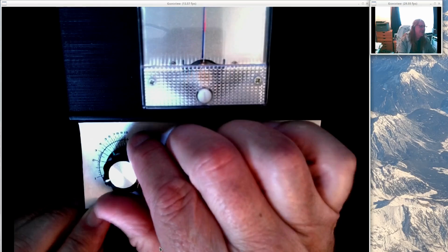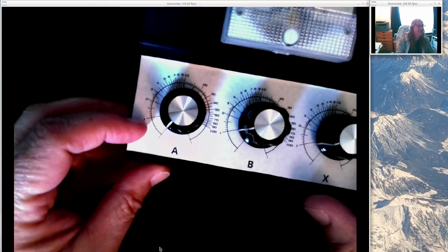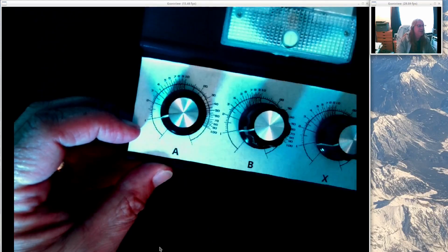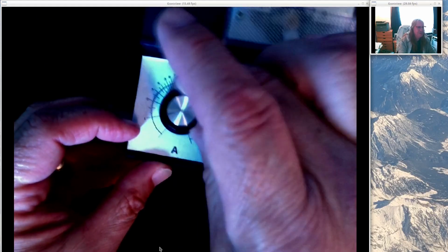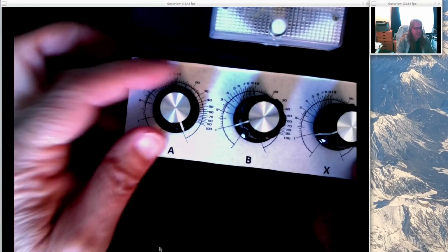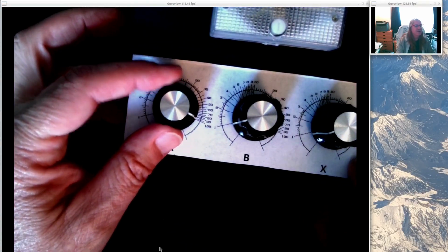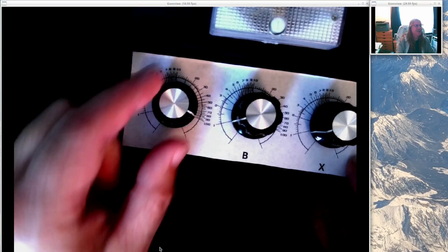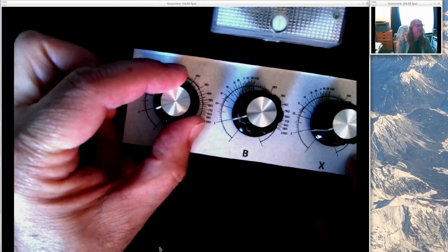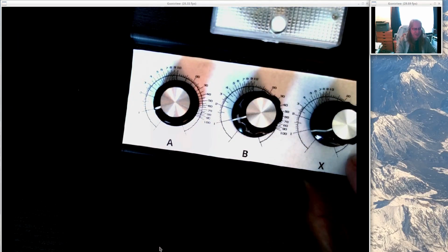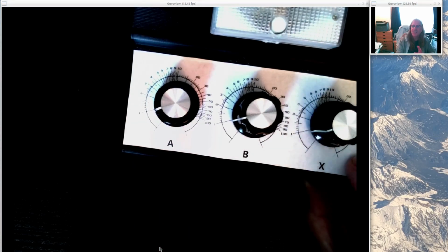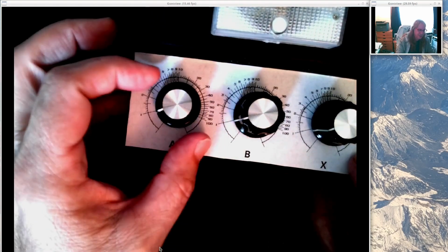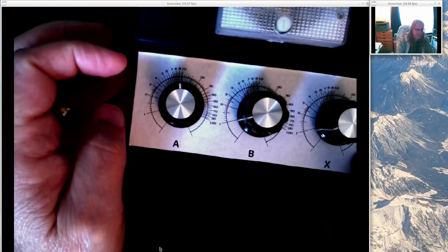So this potentiometer over here will turn all the way over to that position, but that's not where my dial begins. My dial begins right here with the number 1. And it will turn all the way over to this position, but my dial ends right here with the number 100. And so the full range that I'm considering for this potentiometer is from here down to here, with the hopes that I would be using this variable resistor mostly in the region where the change in resistance is linear, right? So it's got a linear relationship with the position of this.